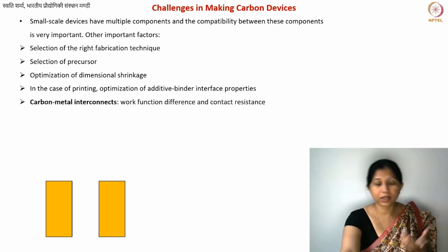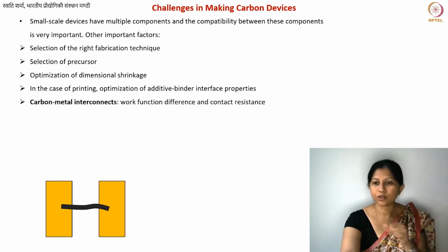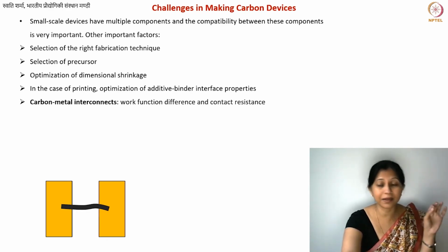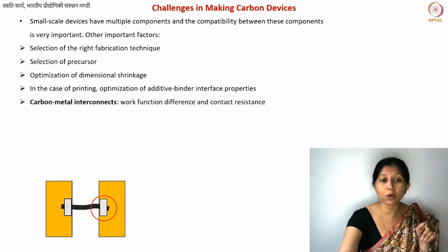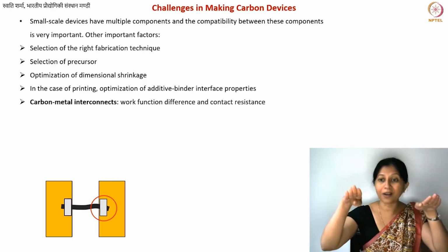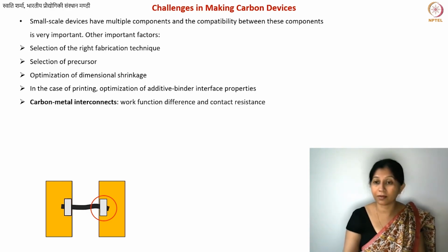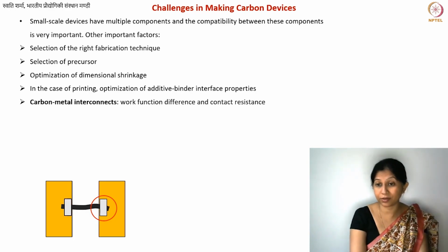What you typically do is, let's say here I have a metal or any substrate, and then I have a carbon nanotube. Somehow I was able to place it on top of that. Single carbon nanotubes, it's nanoscale, right? But somehow, let's say, under the microscope, using certain specialized techniques, I was able to place this carbon nanotube across this contact pad. But now I need some other sort of glue. That glue could be another metal. It can be platinum. You can use ion beam deposition of this platinum. But you need something else to hold your nanotube there.